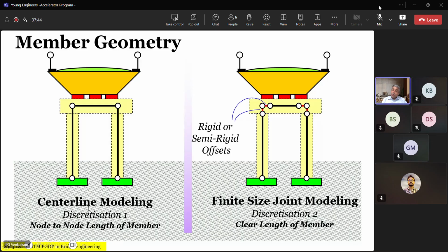Now we come back to the same old question. Let us now go back to your traditional, significantly largest number of structures that you have done. So when you do the left hand model, what are you doing with the flexibilities and rigidities? Left hand model, you say that's the one you should do more, and you said you prefer to do it because you get higher stress resultant.